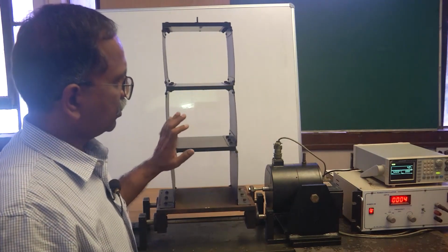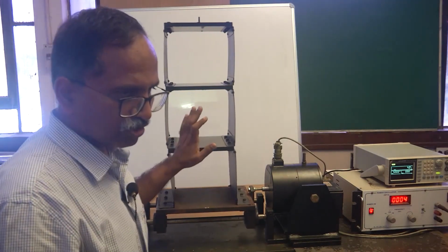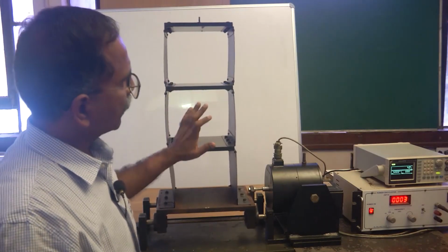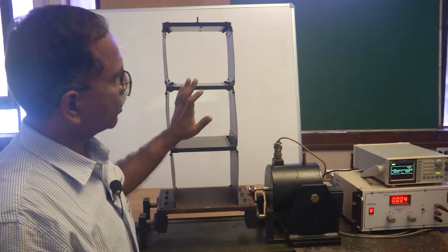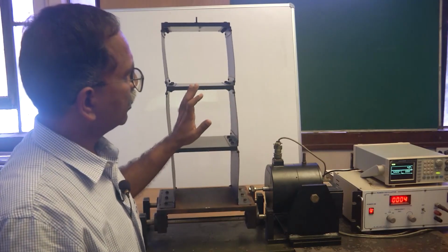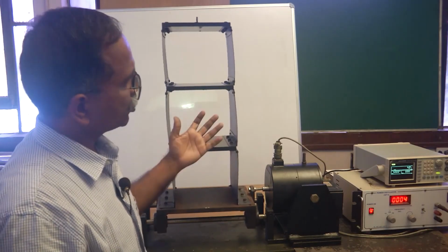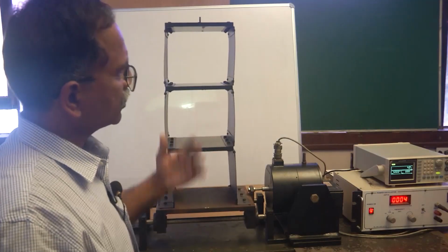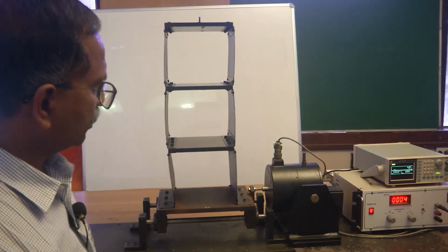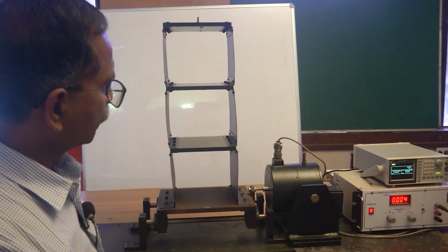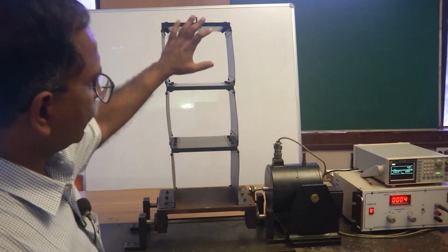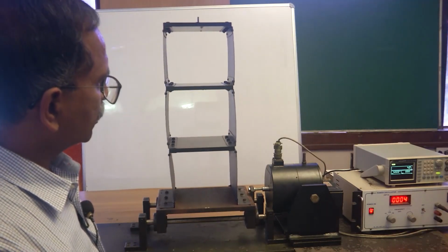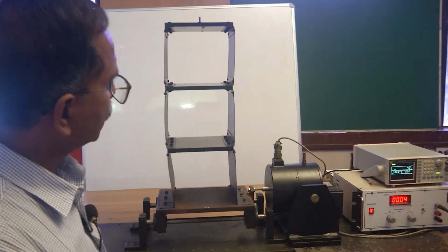That's how you can figure out or verify the mode shapes corresponding to individual natural frequencies. We are of course not getting a free vibration response. We are getting a forced vibration response, but the mode shapes are basically inferred from the operating deflection shape corresponding to the resonance points. So this is the second resonance, or second natural frequency, and the mode shape that we are observing corresponds to the second natural frequency.